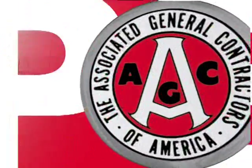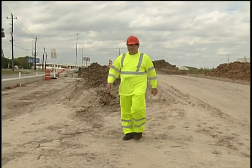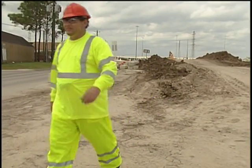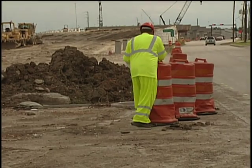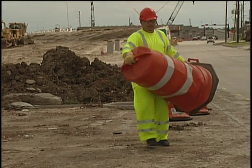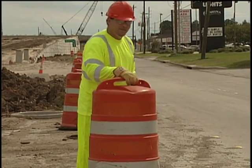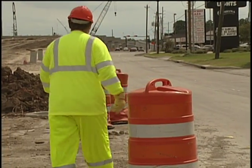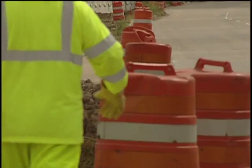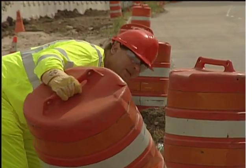Class III garments provide the highest level of visibility and are intended for workers who face serious hazards and often have high task loads that require attention away from their work. They are also recommended in areas where employees may be exposed to traffic speeds of 50 miles per hour or greater. Garments for these workers should provide enhanced visibility to more of the body, such as the arms and legs.